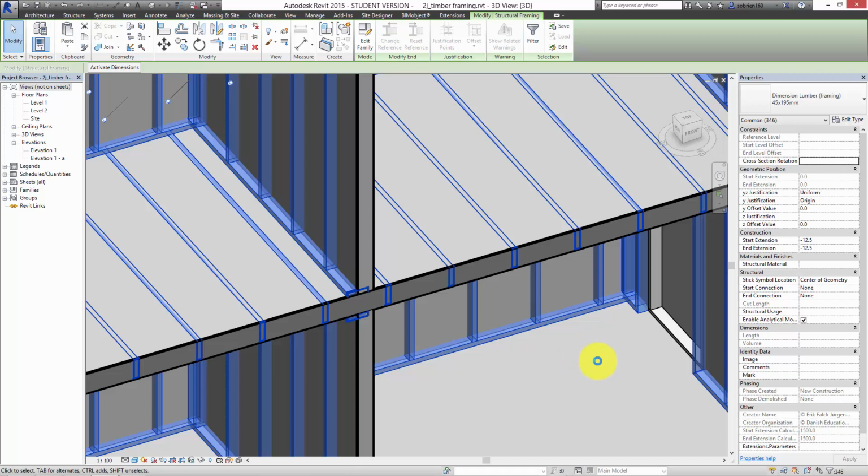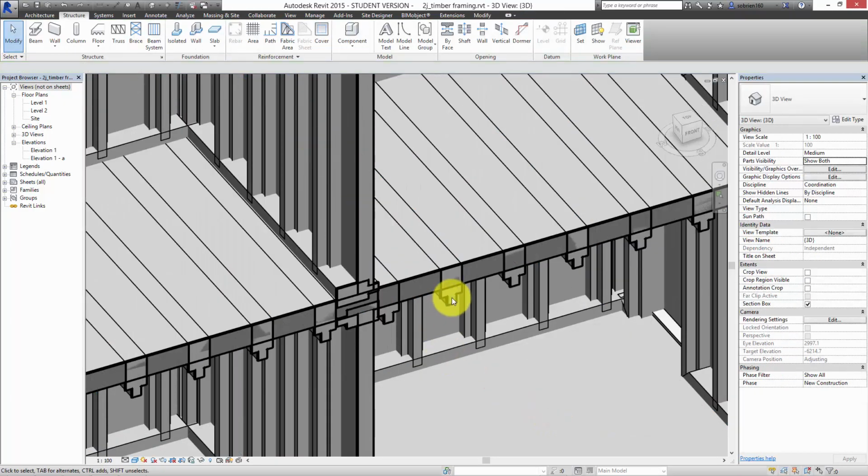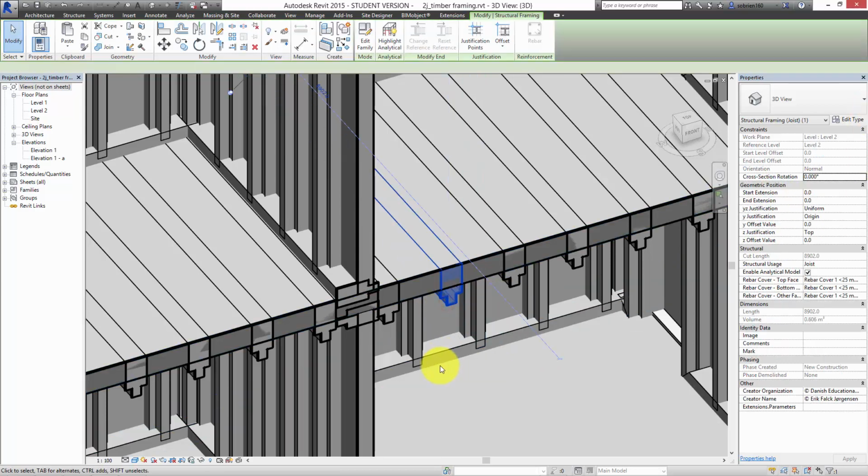And because it's maintaining the same parameter in terms of length, all we're doing is changing the profile of it. You get something like that. You know, it doesn't make any sense in a timber frame, but if you're making it in concrete, it would have an effect that would be useful. So basically anything that you're doing in structures, you can modify the shape of it to whatever you want. So it's simply just the length of it, which is a parameter that's over here. And then there's the profile. So the profile is where you have to edit it. And that's pretty much it.